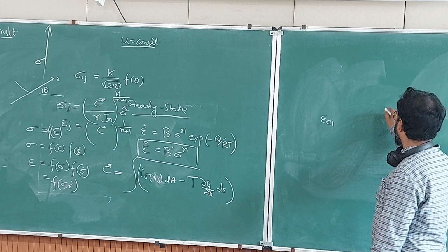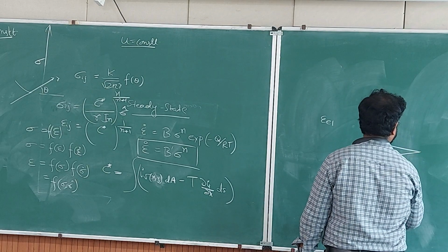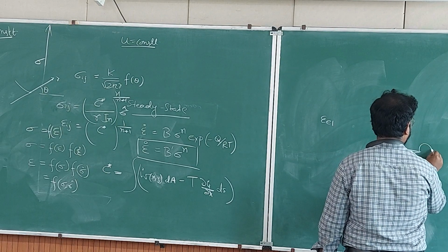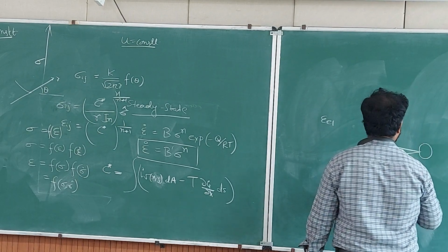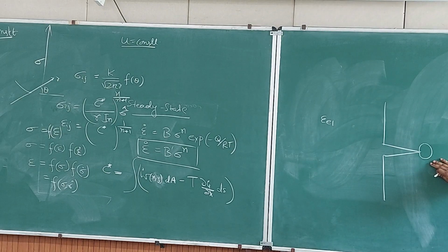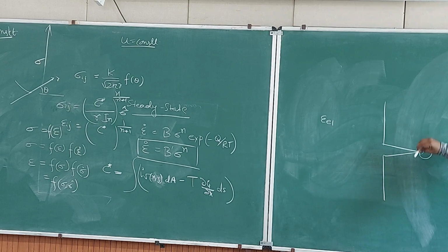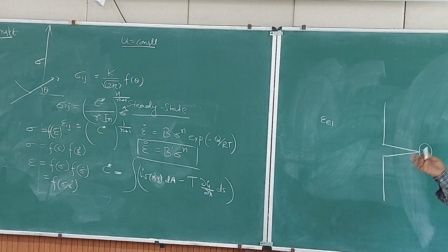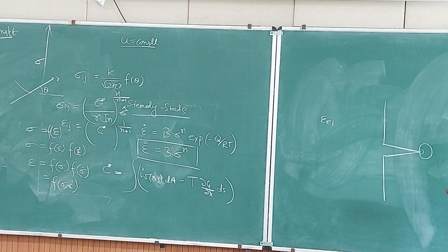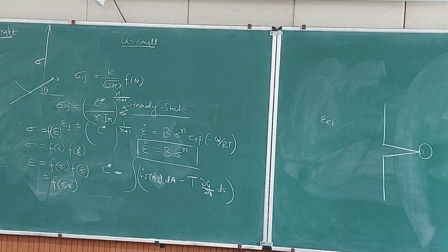So when we have a crack situation, initially there can be a plastic zone, a deformation zone formed because of time independent phenomena, and you will have a creep zone. So the time dependent deformation will start increasing, although there is no clear cut boundary between these two, because really dislocations are moving and then they start climbing. So there is no physical boundary there.